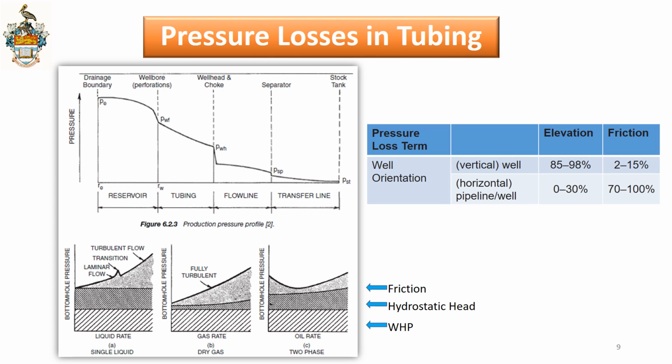And just close to the wellbore, there's a significant pressure drop that takes place as you move through the completion. And that brings you to PWF, which represents the flowing bottom hole reservoir pressure. And from there to PWH, that's the pressure loss that would take place in the tubing itself, which we're going to talk a little bit about a little later on. But from the wellhead, you would have a significant pressure drop there across the choke. So that's what that big pressure drop represents.